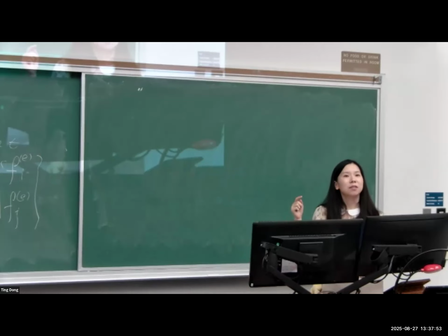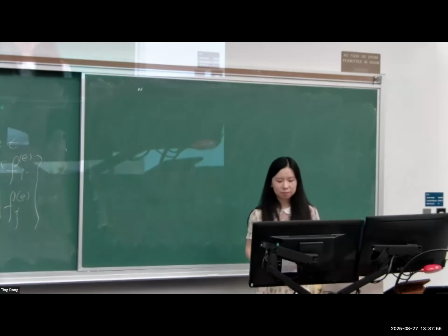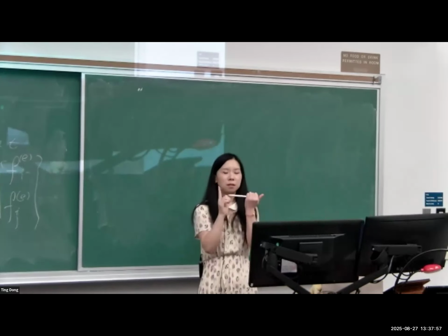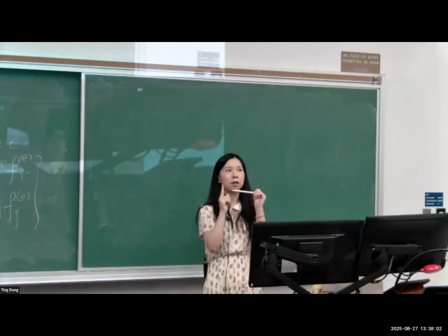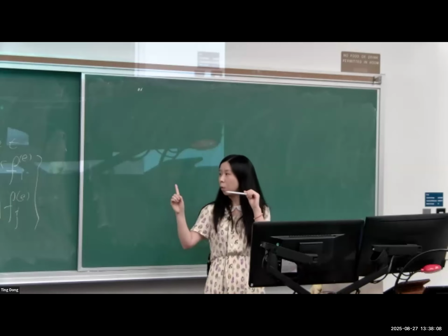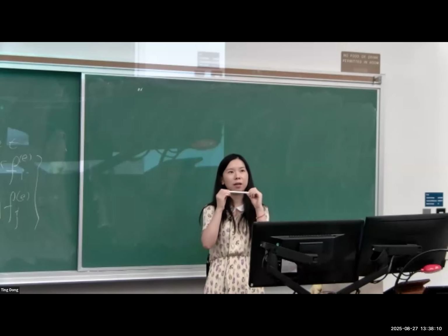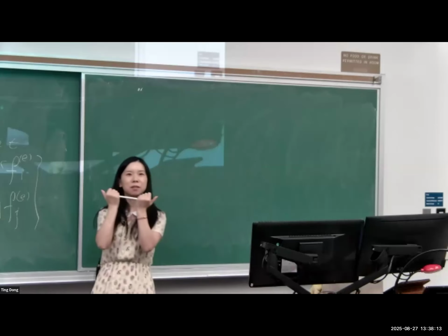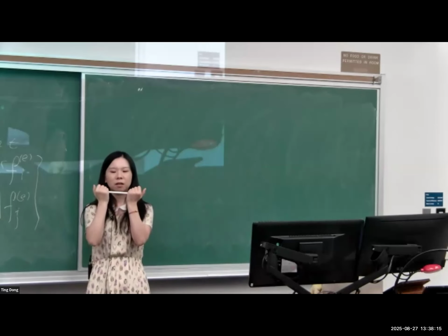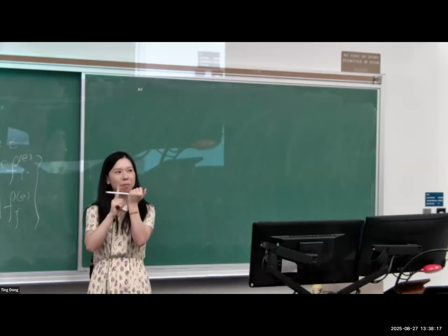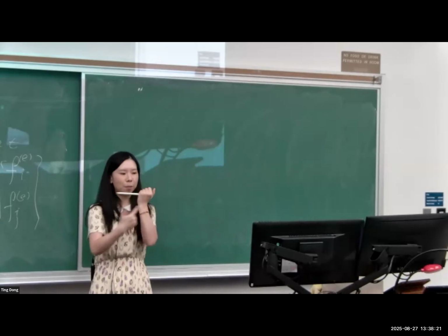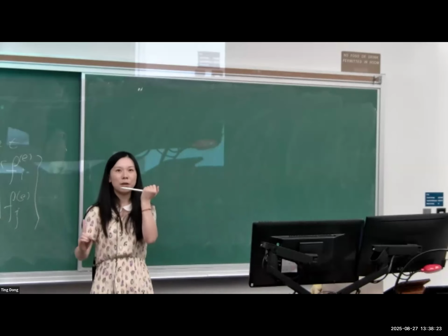Staying still. Well, let's say I have a spring element. Let's say I'm standing here, and the displacement at the j node is 0.1 and this one is 0. This could be one set of solution. And now I have the same force, I move here, and I have the same tension, same force in this spring element, but the displacement could be, let's say I move 1 meter to the right.